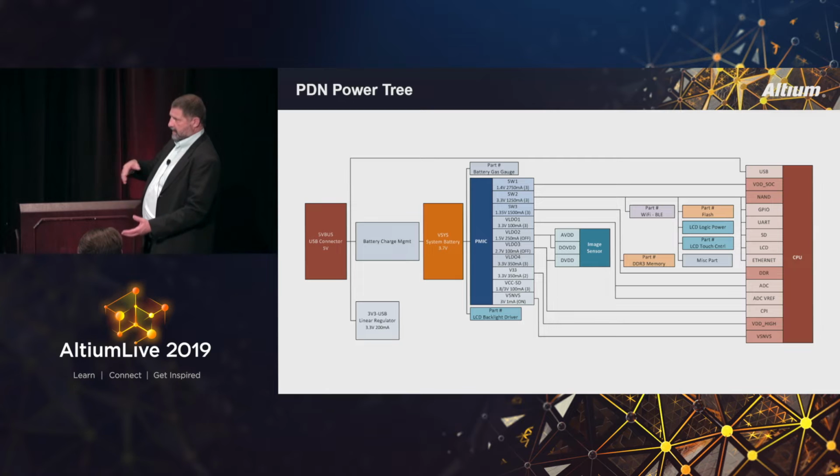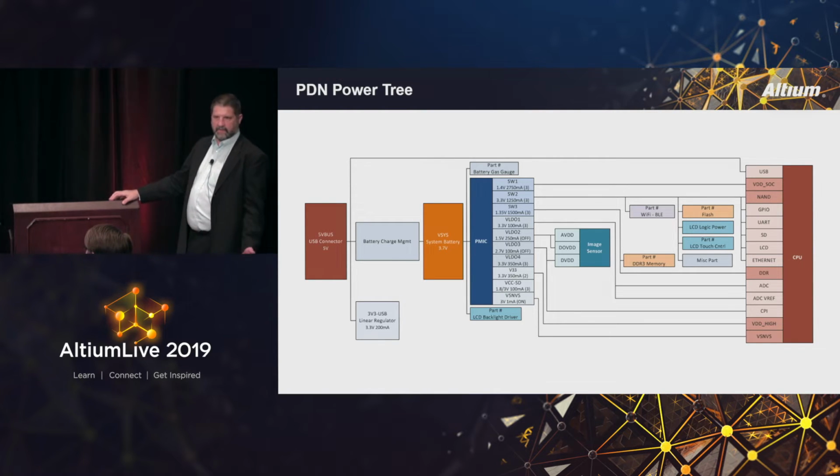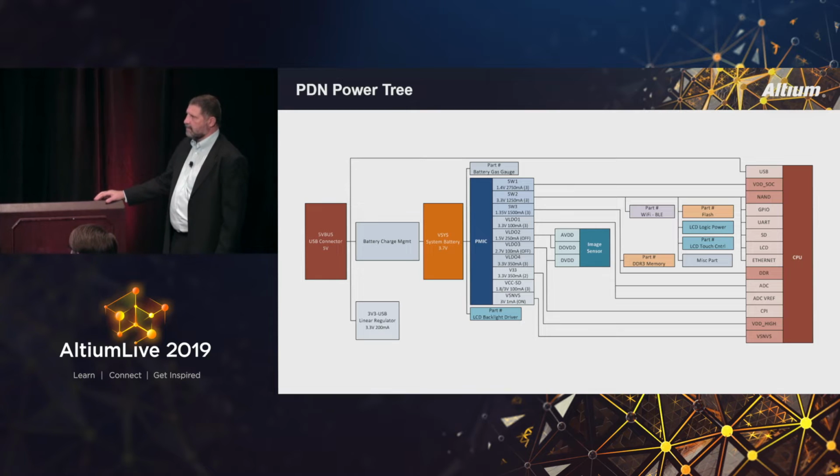Usually that PMIC is going to have all the power that it's generating, but it's also going to have the sensing for that, and that's a very critical aspect to controlling the noise on your PCB. And then once we get out of that, we see maybe some voltage dividers, creating the different nets that are going to get to the components and the component functional blocks near that CPU. So that PMIC is going to be a super critical part of the layout.